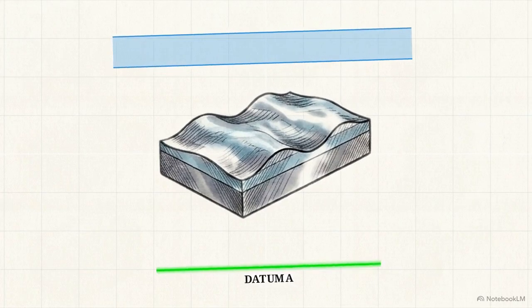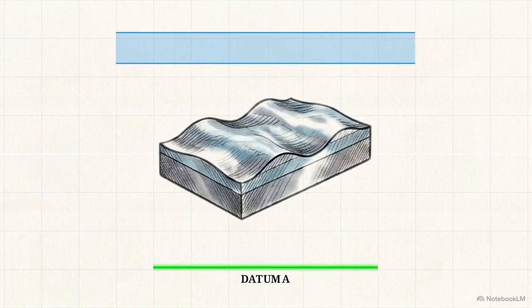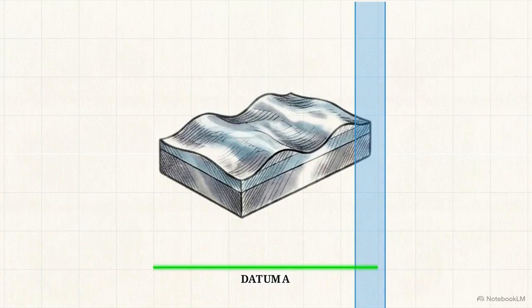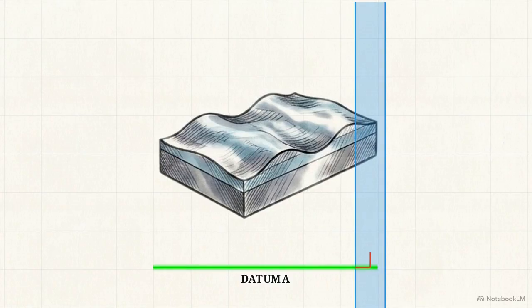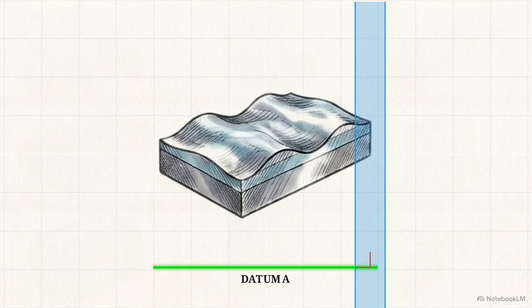Parallelism introduces an anchor. Here, the two transparent planes are locked perfectly horizontal relative to a highlighted base, known as datum A. The surface must be flat, but it must also maintain a 0-degree relationship to that base. Perpendicularity operates on the exact same logic, rotated. The tolerance zone now stands at a perfect right angle, rigidly locked to datum A.